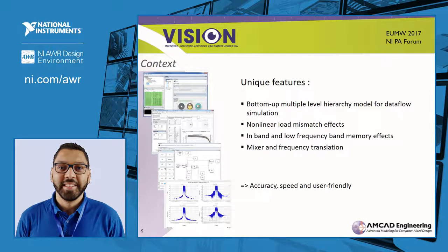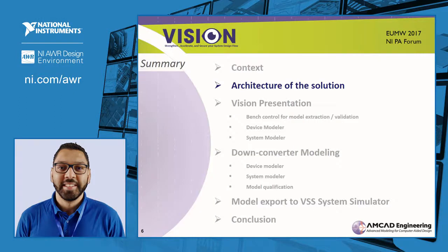The unique features are a bottom-up multiple-level hierarchy model for data flow simulation. Behavioral models take into account nonlinear load mismatch effects, in-band and low-frequency memory effects. In the modeling of your system, you can include a mixer or frequency converter. The main goal is to provide you accurate models, speed up your simulation, and have a user-friendly environment.